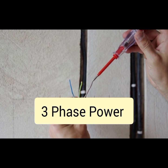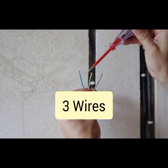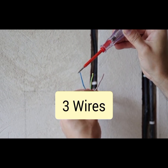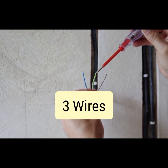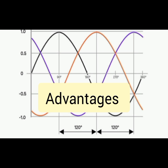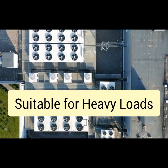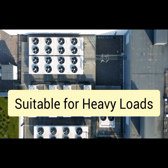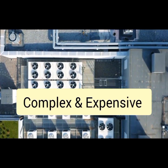Three-phase power is a type of electrical power distribution that uses three wires, three hot wires and one neutral wire, to transmit AC. The voltage in a three-phase system oscillates between positive and negative values, creating a sinusoidal waveform that is offset by 120 degrees between each phase. Advantages: higher power capacity and efficiency. Suitable for heavy industrial loads and large commercial applications. Smoother power delivery. Disadvantages: more complex and expensive to install. Requires more wires and equipment.